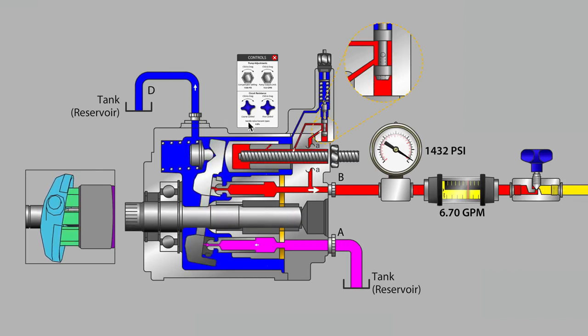In addition, a blocked case drain line will cause our pressure compensator function to misbehave or cease entirely. The malfunction may be that no pressure compensate function is available. So again, the pump could easily move to a catastrophic state without maintaining case drain flow. But all of this case drain flow occurring, of course, is a loss of fluid at the high pressure that otherwise could have been available to us on the outlet and sent to hydraulic valves and cylinders. So we've paid the price of volumetric efficiency.